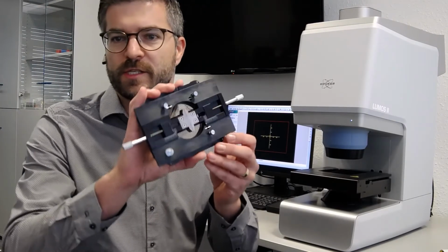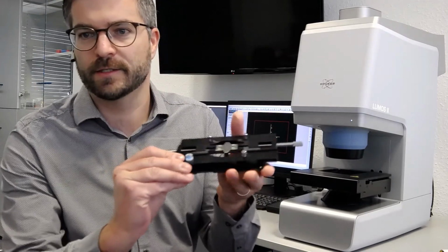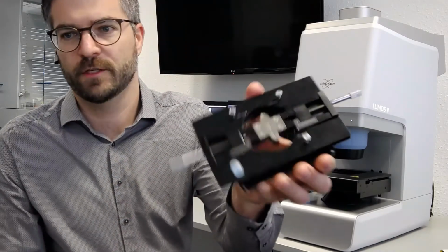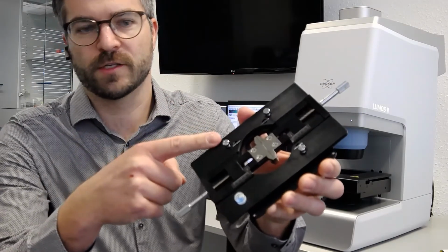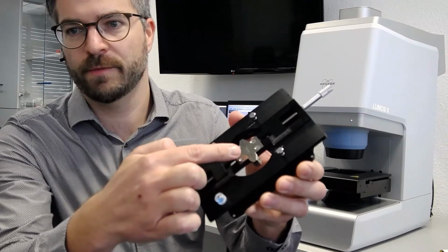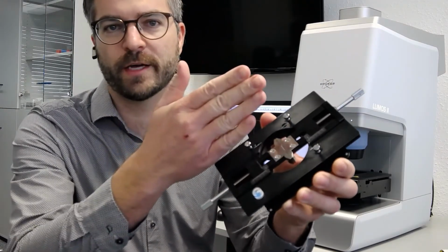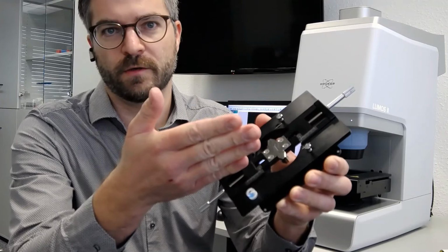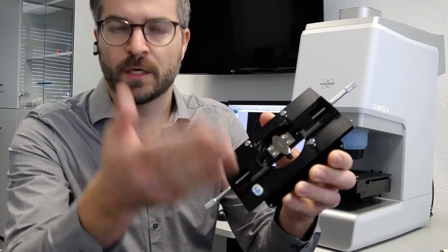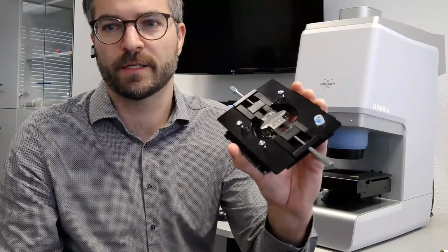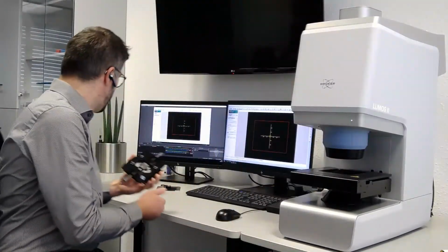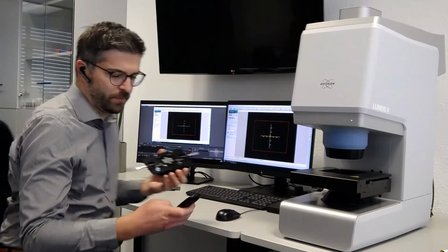And that's the result. This is exactly the sample like we have seen in the video. We have this microvise holder, the two metal brackets in here, and in between we have the PTFE bracket, our sample with the EVOH oxygen barrier, and on the other side the second PTFE bracket. Exactly this sample we will now bring into our microscope. Therefore, I zoom in to the sample stage.